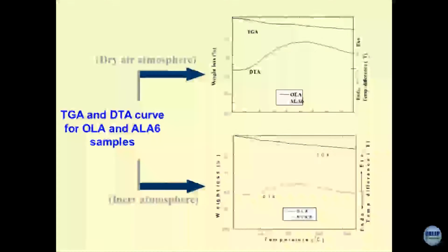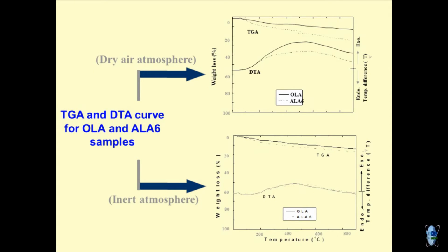For that there is another equipment which is known as DTA, differential thermal analysis. So this is thermogravimetric analysis and differential thermal analysis. As the temperature increases, and the increase in temperature is controlled, that means the rate of enhancement of temperature can be fixed, depending upon the response which you get, I can define a reaction as exothermic or endothermic.